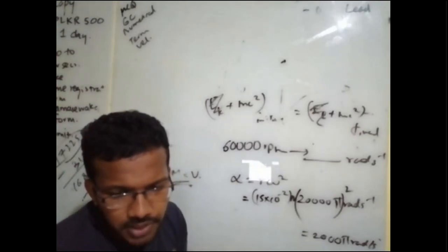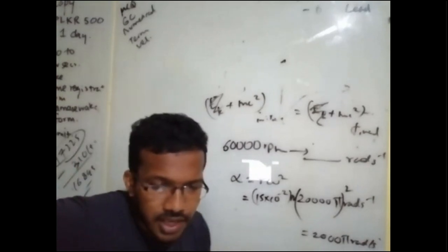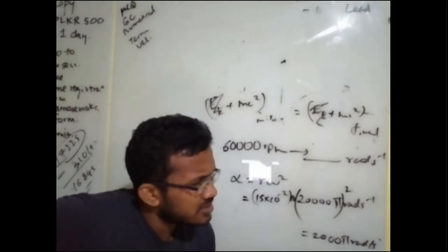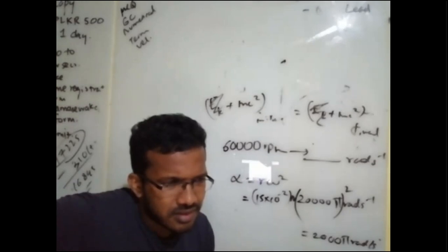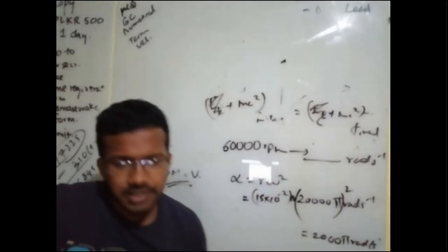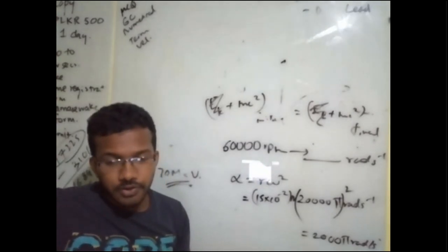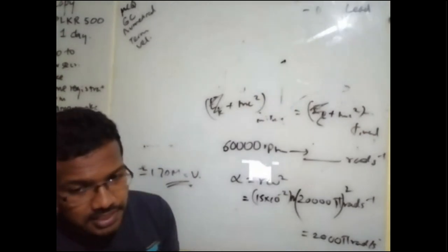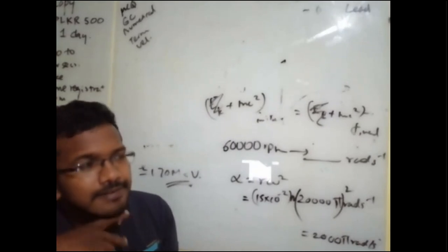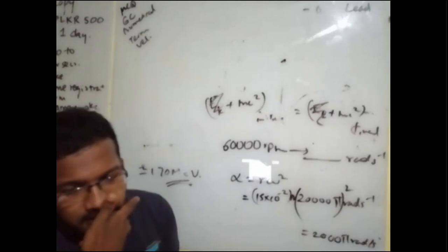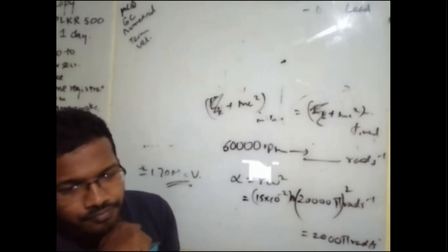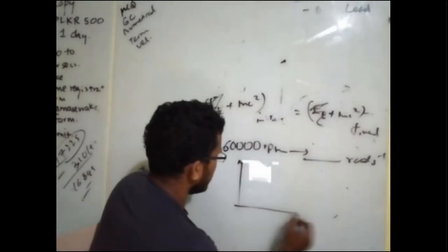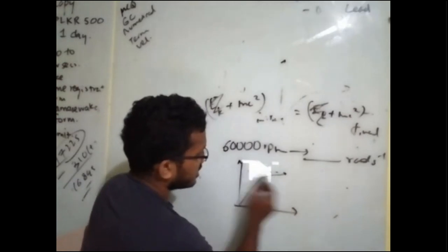The rotor is subject to forces. Give two mechanical properties essential for the material from which the rotor is made. This is asking for unit 1 actually, and a little out of syllabus also. That means strong and probably stiff. Strength is related to ultimate tensile stress. That is still in the syllabus. Wait, you are in the old syllabus, no? Okay, so then for you it's there. Strength refers to the ultimate tensile stress that it can bear without breaking. And then I think toughness also. Toughness refers to the amount of energy it can absorb before fracture. So the people in the new syllabus can identify this, the breaking point.